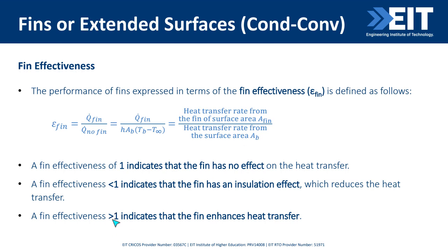Yes, good. In fact, practically it should be as high as possible. It should be more than 3, 4, 5, or 10 times more than without fins. Then we can say, yes, definitely we can go ahead with fins. But it is also practically possible that after using fins, we may get effectiveness less than 1. Then there is no point in using fins. So fins should be used only when it is necessary and only when the effectiveness is greater than 1 theoretically.